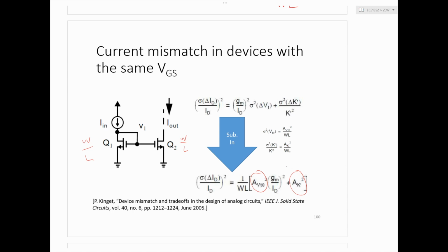Okay. So the main purpose of this, the arithmetic here is one thing, which is not that complicated, but actually simulating this is a bit of a challenge. It's something you may or may not have done before, right? So it's a bit of an exercise just to figure out how to set up a simulation where the transistor parameters will vary randomly, and basically the approach that's used is to conduct what's called a Monte Carlo simulation, which basically means you simulate 100 times with random variations on these parameters. And that's the final sanity check that says, yes, I've sized it right.